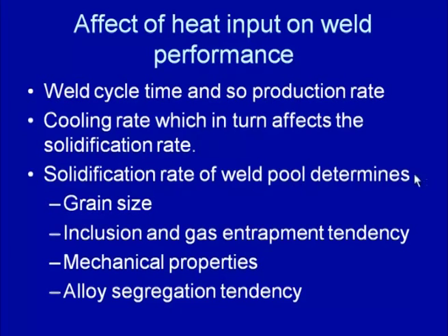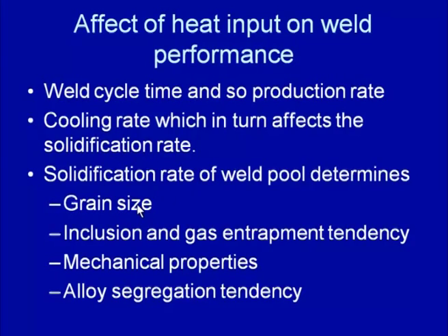For example, the higher the cooling rate, the higher will be the solidification rate, and the lesser will be the time required to solidify, which in turn will decrease the grain size, because each microconstituent will not get enough time to grow to a large extent.